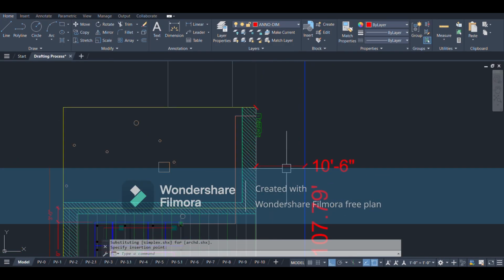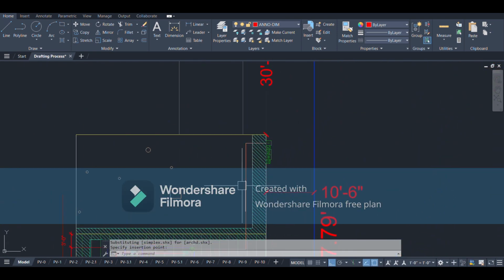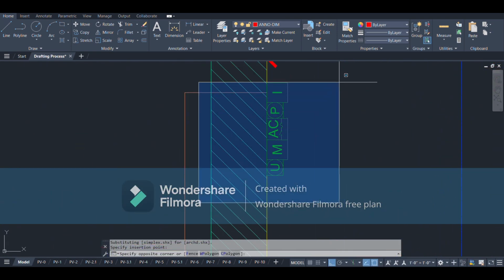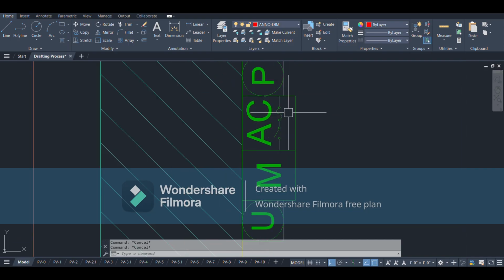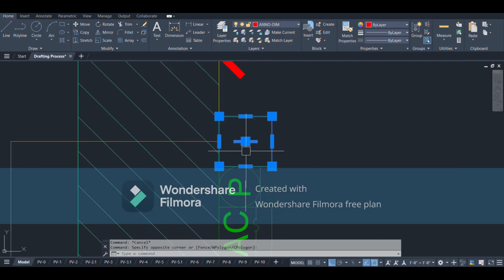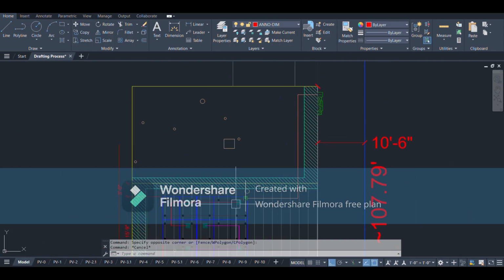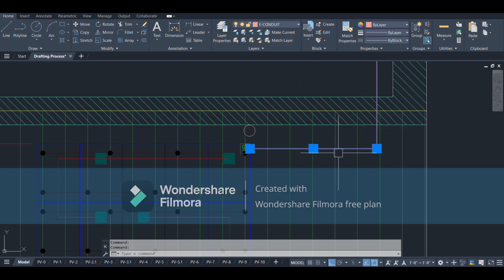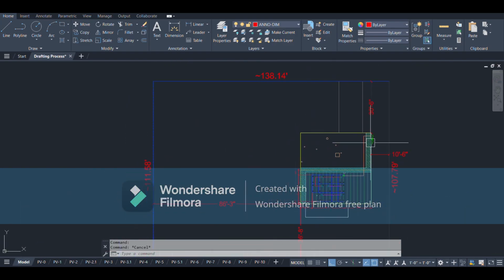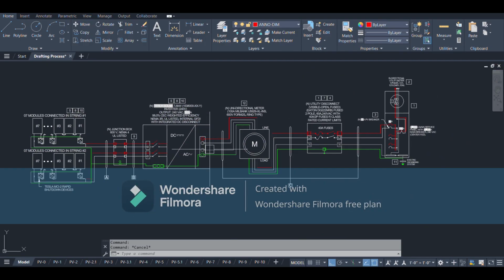Step 5. Electrical details. Once the module layout is ready, I move to the electrical part of drafting. I start placing components such as inverters, disconnect switches, combiner boxes if needed, main service panel or load center. Then I draw the conduit path from the modules to the inverter and from the inverter to the main panel. I make sure the path is logical, clear, and not too complicated.